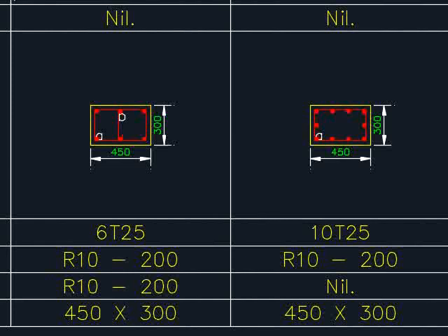There must be a reason for that, and if you confirm the design is correctly done, then you have no choice, unless you would like to revise your structural key plan to have the columns more equally spaced, so that there won't be significant variations in terms of the loads on the columns.